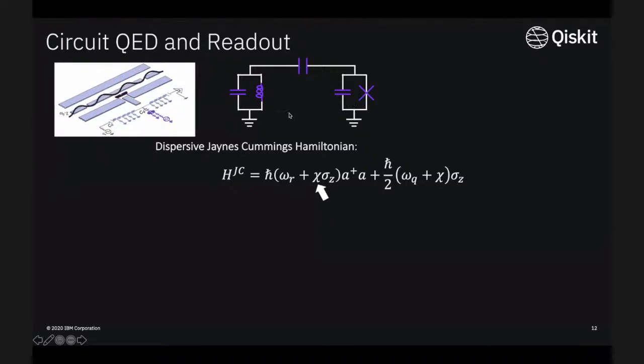But so this here is showing the physical realization of such a system, say, in which you see that linear transmission line here. So this element here is going to be your simple harmonic oscillator. So this part right here is this. Then your transmon ends up being something that's sitting right here. In this case, you have some control line that allows you to tune this transmon in this particular case. And then it is now capacitively coupled to this through just sort of some coplanar capacitance between the center line and the transmon that you're interested in.